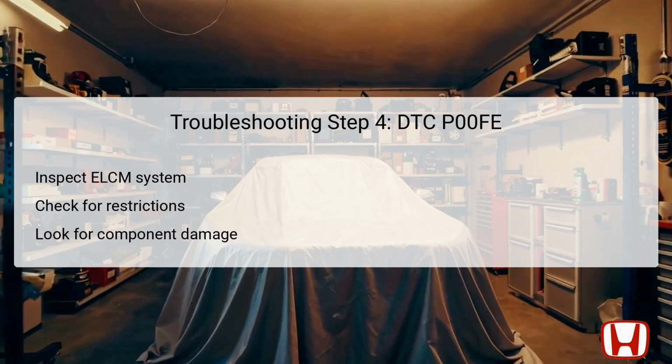In the fourth troubleshooting step, you will focus specifically on the ELCM system. This inspection involves checking the entire system for any blockages, restrictions, or damage that could be affecting its performance. Components of the ELCM must be assessed visually and physically to ensure they are free from debris or damage that could hinder their function.